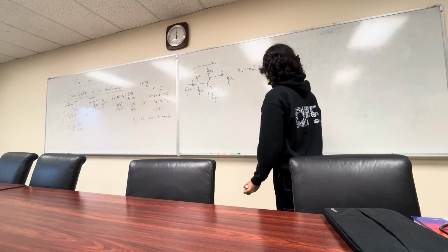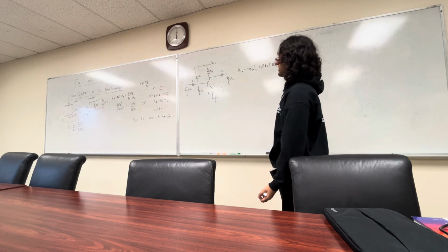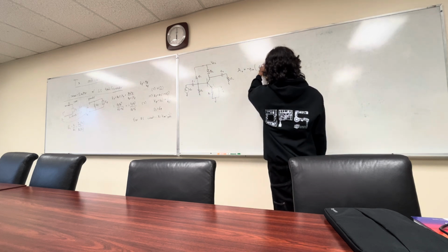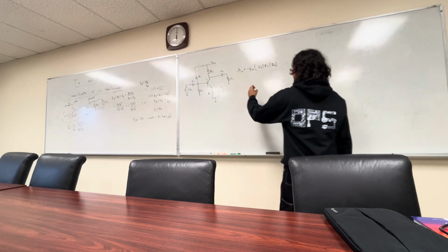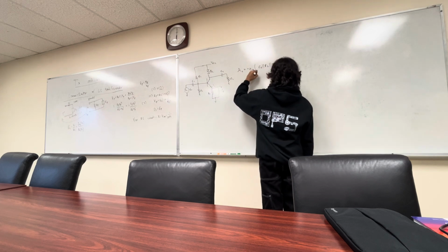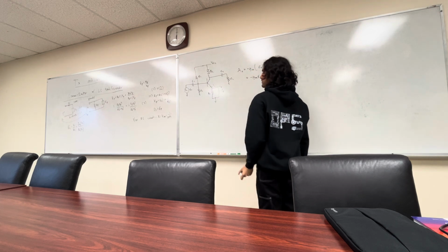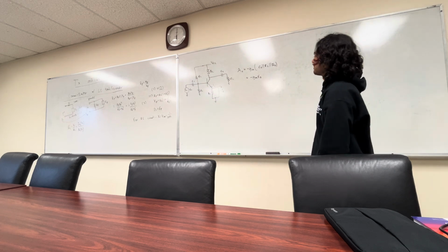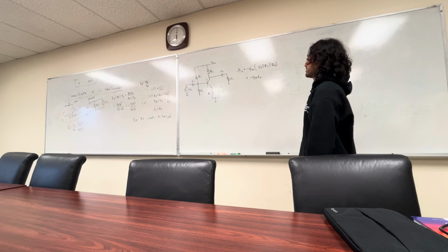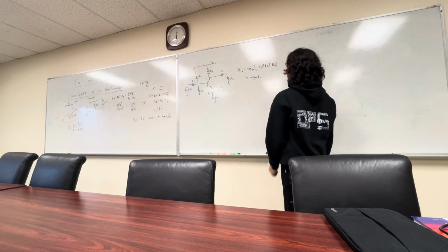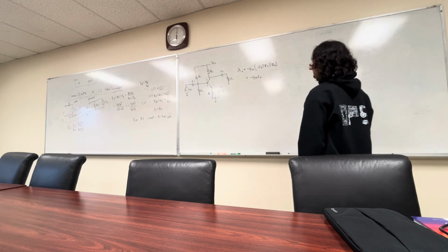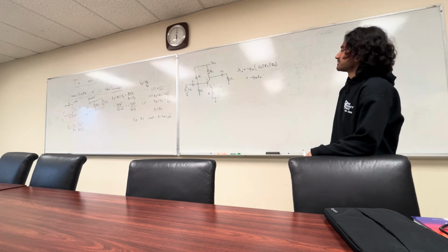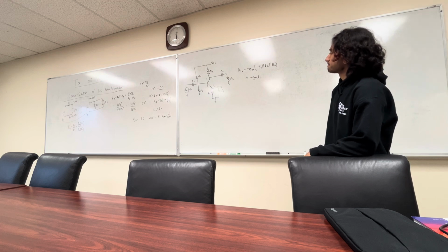RL, okay? And we surmised that the highest gain we can get, this is a parallel function, is if we make RC infinity and RL infinity, the highest gain we get is negative GM R0. Can't really bypass this value, ever. By definition, we can't bypass it. So what do we do to try and get our RC and RL to infinity? If we get that to infinity, we maximize our gain. Seems like a pretty good idea, right?